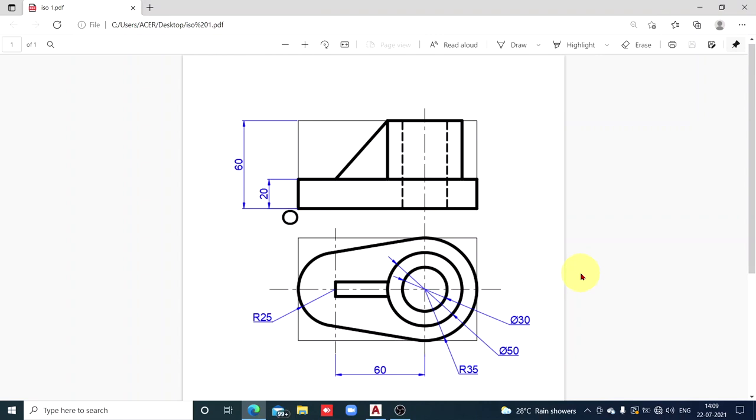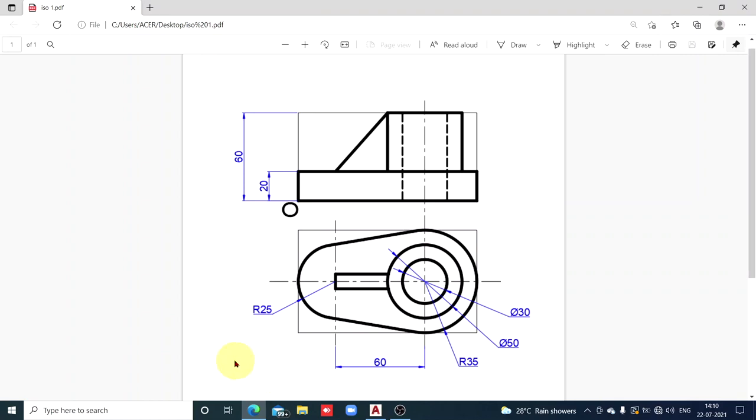In the front view or in the top view, check on which side point O is mentioned, whether on the right side or on the left side. And in the isometric view, on that side you should consider the width axis. Left side axis is the width axis.